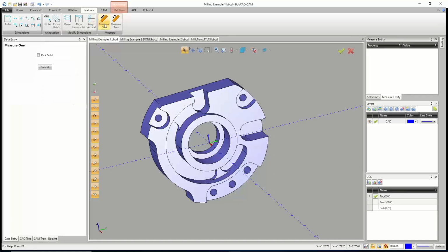So for measure 1, I'm going to start by picking these holes here. I'm going to find out if these are all different sizes. So we've got a 3/16, 3/16, and 3/16. So we're going to need a 3/16 drill. Perfect. We're also going to need a center drill. I primarily use 90-degree spot drills. I like them a lot. I just like spot drills more than I like proper center drills. You can use whatever you want. This is a list of tools we're putting together now so that we can pick the tools and put them into the crib. So I've got a 1/2 inch, 90-degree spot drill that I'll use for that part of it.